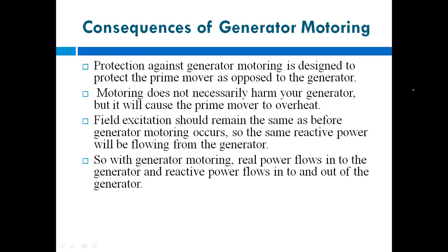So the same reactive power will be flowing from the generator. If we keep this field excitation the same, then the same reactive power will flow from the generator. Otherwise, we have seen what happens if there is any fault: the reactive power increases to 2 to 3 times.